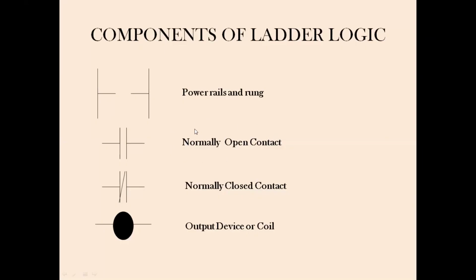So what is this normally closed contact? It is just the opposite of the normally open contact. Fine. So if we think about our truth table for the normally closed contact, we have one input and one output. Since I have mentioned it is opposite to the normally open contact, what will be the first case of the truth table? It is 0, output is 1. When the input is 1, output is 0. Okay. So let me show that in a truth table.